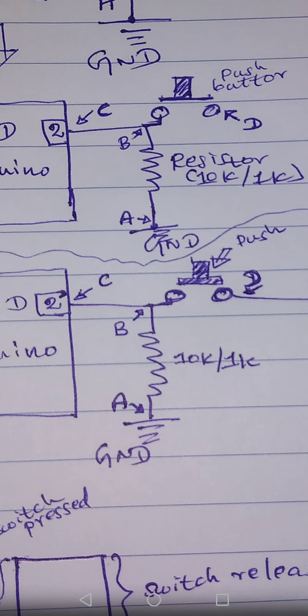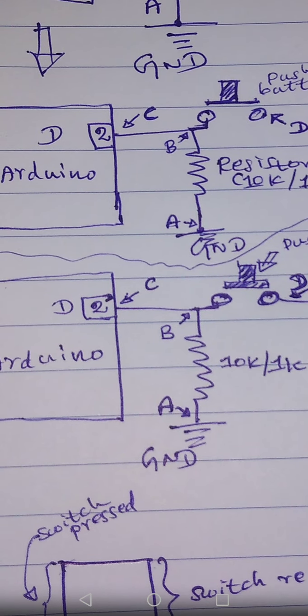And if the customer releases the push button, let's say we digital read the pin number 2 value. That is why I taught you the coding. If you don't understand, go to one of the previous videos where the input coding, digital read coding, is there. Have a look and come back. If we digital read pin number 2 and that is ground value, that means the customer has released the switch. Whatever logic you want to happen when the switch is released, you can make it happen using an if else condition. I hope this is understandable. So you can see now switching is implemented.